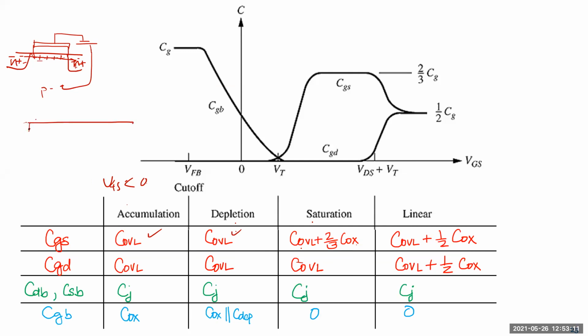If you have the channel, it looks like a small value resistor. So you have the source side, you have the drain side, right? When the channel is completely formed and I want to represent the cap, that's the best I have, because I can't put 2/3 and 1/3 here, as that will be an underestimation. Because it is resistive, doing this half-half is very close.